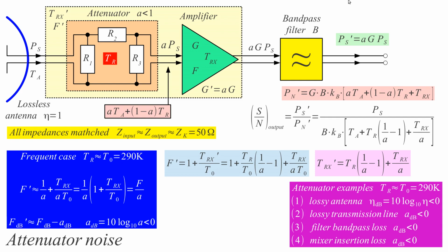it is very useful. If I have a receiver that has a 5 dB noise figure and I have minus 2 dB of attenuation in the cable, then the noise figure of the whole connection will be 5 dB minus minus 2 dB, so we get 7 dB. It's a very simple calculation in many practical cases when we actually need these things.